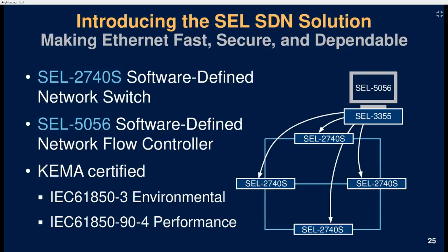This is a family of protocols that are used typically in energy environments. A couple of them being protection traffic and then one of them being automation type traffic. This is a switch that can operate from -40 to 85 Celsius with a wide range of humidity. It has been vibration tested and ESD tested to the point of breaking. The requirements for a substation is 6 kilovolts contact and 8 kilovolts in the air.